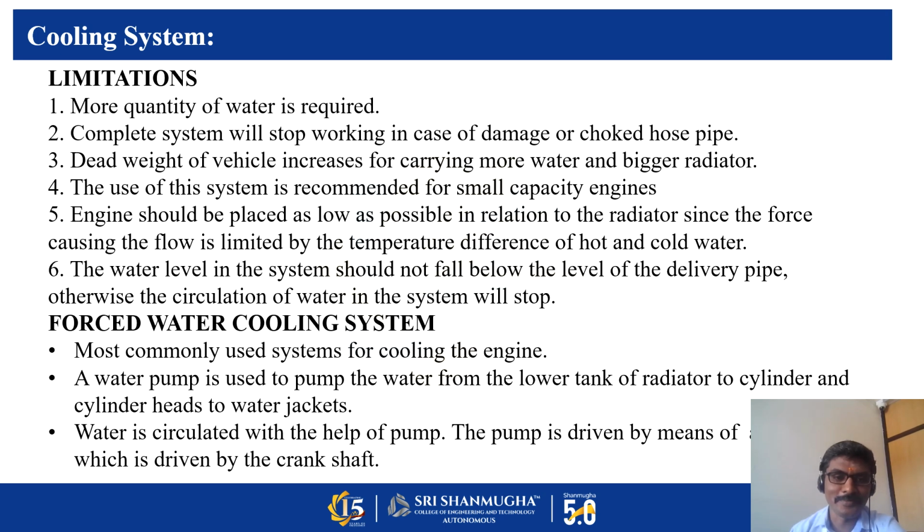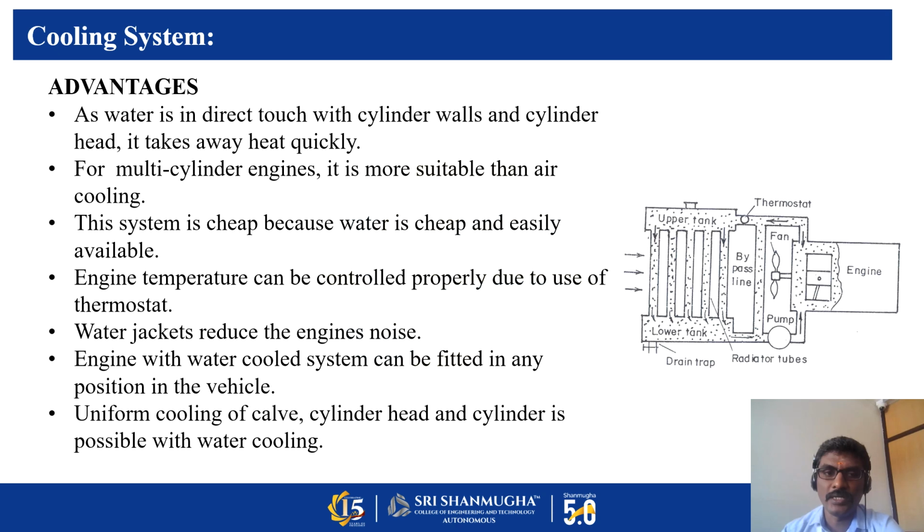Forced water cooling system. Most commonly used system for cooling the engine. So a water pump is used to pump the water from the lower tank of radiator to the cylinder water jacket. Water is circulated with the help of the pump. The pump is driven by a belt which is driven by the crankshaft. Advantages: as water is in direct touch with the cylinder walls and cylinder head, it takes away heat quickly. For multi-cylinder engine, it is more suitable than air cooling system. This system is cheap because water is cheap and easily available. Engine temperature can be controlled properly due to use of thermostat.